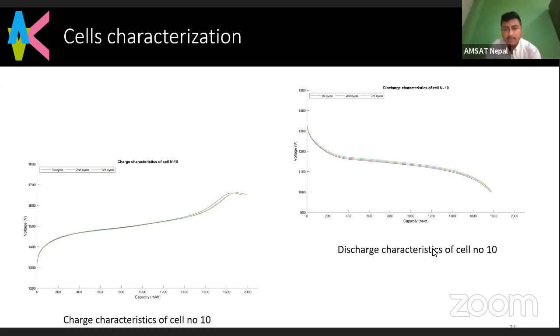So what about the cell balancing, since you use a 3s2p configuration in the battery? Is it similar to lithium ion or different? If we use lithium ion battery, we don't need more batteries. In our nickel metal battery, we put 6 batteries, 3 in series, 2 in parallel. But if we use the lithium ion battery, only 2 is enough. But cell matching is important, yes.